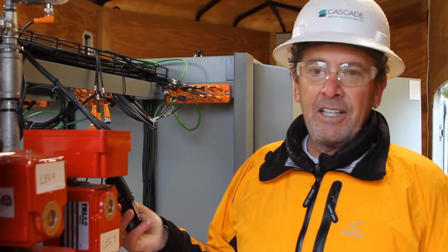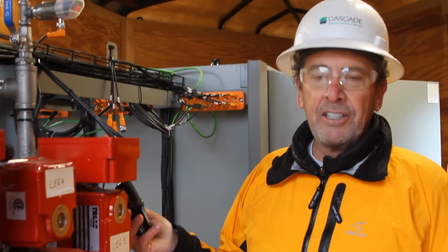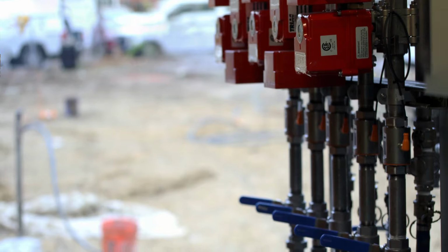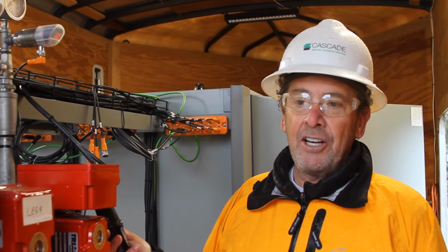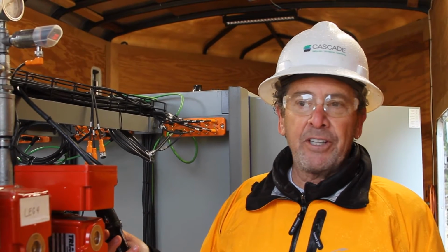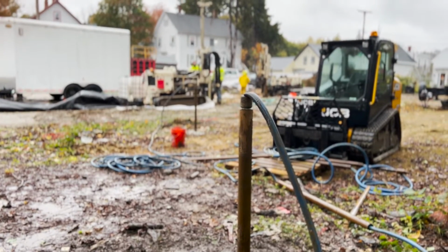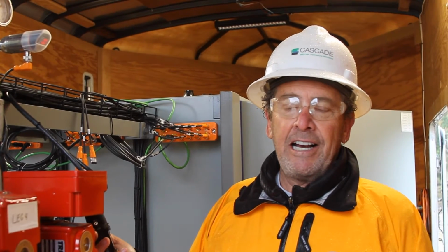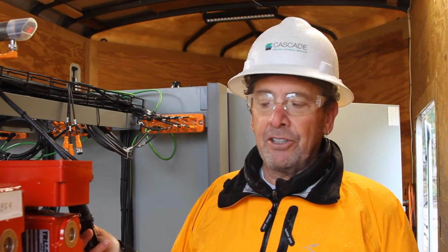So what we have right here on the right are our automated control valves. They're tied into our pressure and flow control points, and they open and close to maintain that pressure and flow throughout the injection. Whether we're going into a well, where we'll be at more of a consistent flow rate and pressure over the duration of that injection point, or, as at this project, going through direct push points where we'll be maintaining flow and pressure in each interval that we're targeting with our direct push screen. In this case, it's a 2-foot screen. We're injecting from the bottom up in a sandy interval, and these valves will keep us within the control parameters.